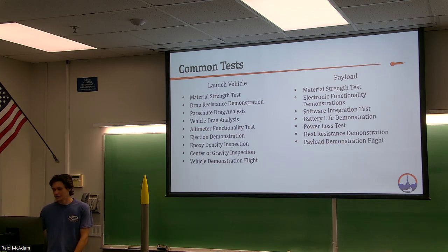And then for the payload, you've got, again, material strength tests. Depending on what you're doing, your payload might take a good amount of force. Like I know last year, for our RC plane, we got told that we had to keep the kinetic energy on landing below 75 foot-pounds,